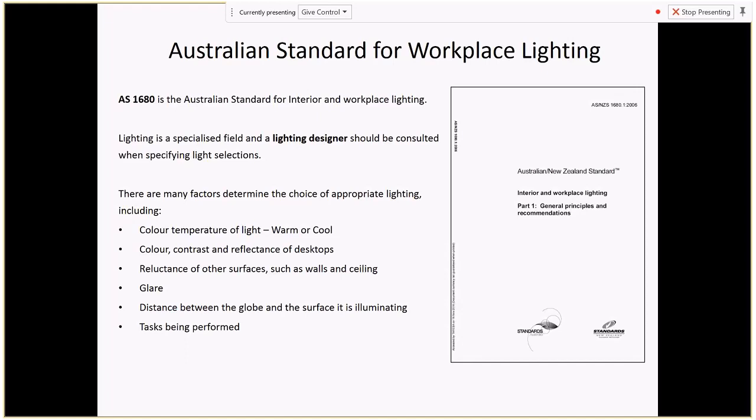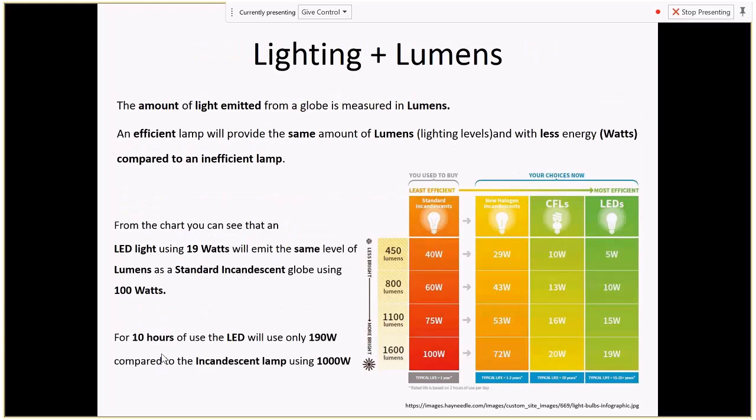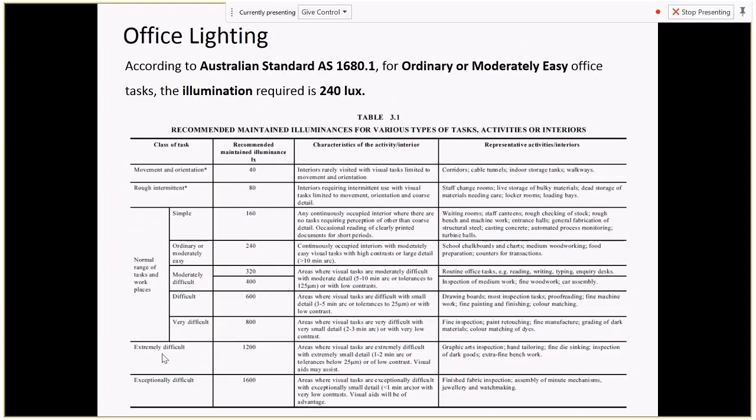We lose efficiency as we move that light source further away. Also, the lighting required is going to be dictated by the tasks being performed. If I'm a jeweller working with expensive diamonds at a minute light level, I'm going to want a lot more lighting into that space, and direct lighting, than I would if it were a romantic restaurant.